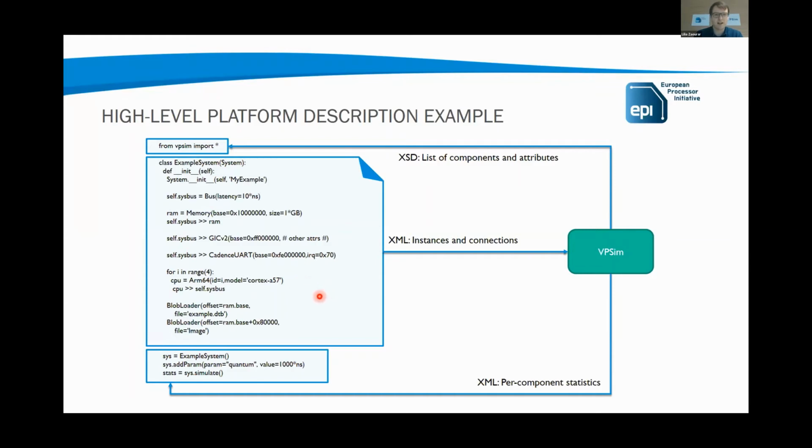Once the hardware platform is set up, we can also give some parameters that set up the software part. Here we are loading a device tree blob in the RAM and also an image file for the OS to run correctly. All this description in Python generates an XML file that specifies the platform that is to be used by VPSim, and VPSim will interpret it to instantiate during simulation the given platform.